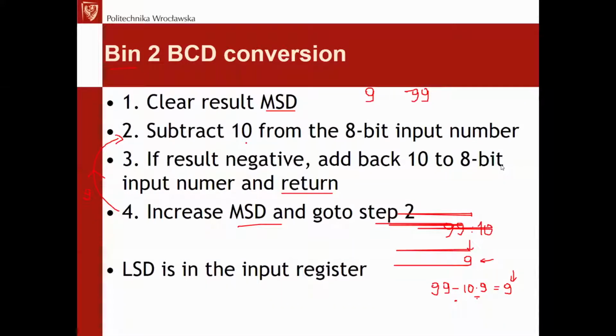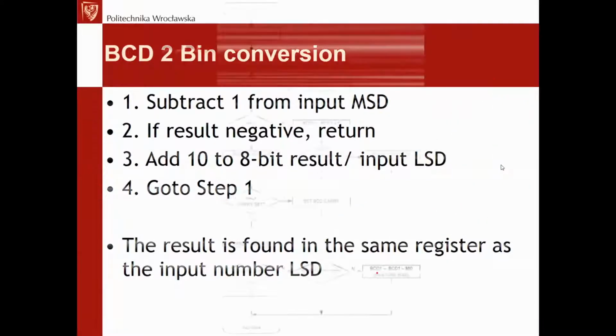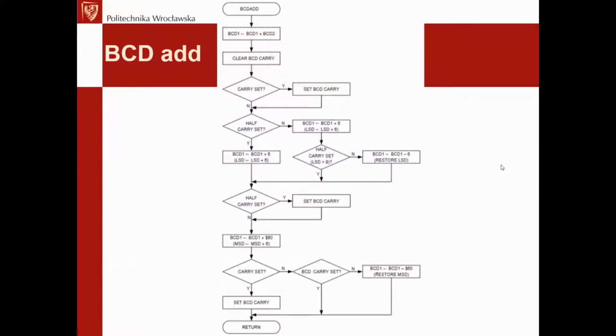Although here it really depends on the microcontroller. So binary to BCD, here there is no rule, because it really depends on the penalty or the price or the complexity of the division at the used microcontroller. Here, usually even at weak microcontrollers, this conversion is simpler than the iterative version.